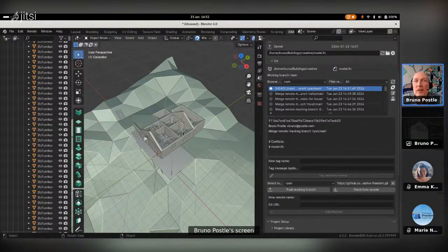As I said, I'm a recovering architect, so I'm not a practicing architect. I have worked as an architect in the past. The practical examples are that quite often multiple people in different companies are working on the same building. The way it works in the industry is that one person creates a model for their particular skill. So the architect creates a model, and then if other people are using different software, so the structural engineer or the services engineer, then the architect will export a view of their model, probably as IFC, and then the other people working on the project will load that as a reference overlay, sort of like a background layer, and then they'll try and do their stuff on top. They'll create their own information, and they'll export this overlay that other people in the project will be able to look at, but they won't be able to modify.